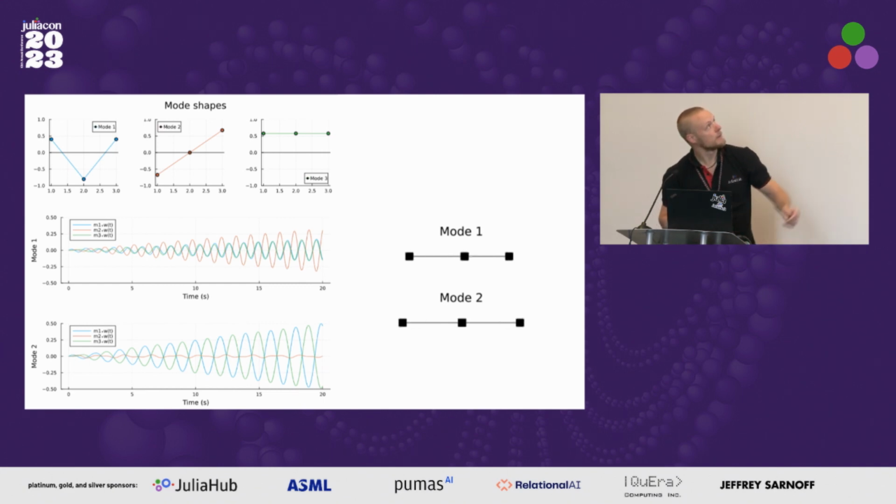So we can plot the mode shape in the top there. We see the first one says that mass number 1 and mass number 3, when they go in one direction, the second mass goes in the other direction. And that's the animation we see on top there. And we can simulate that in time also. We see exactly the same pattern.